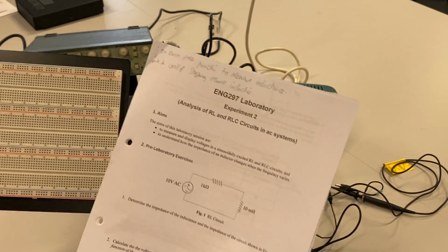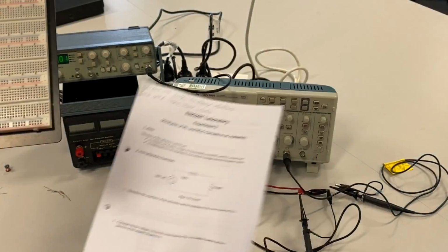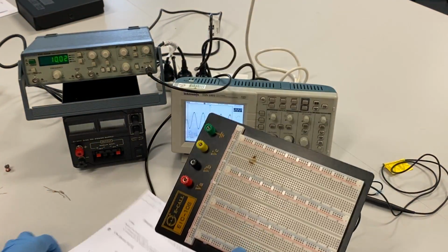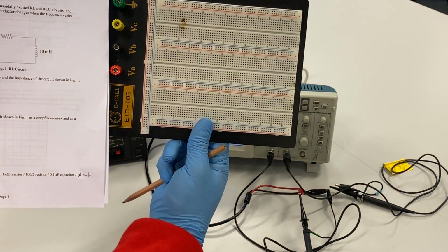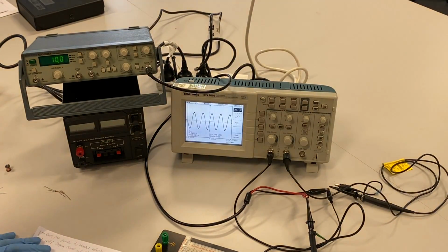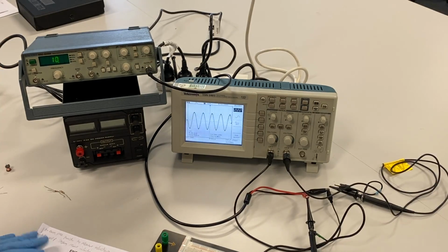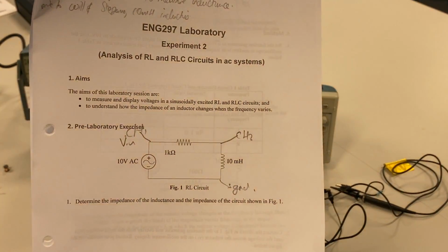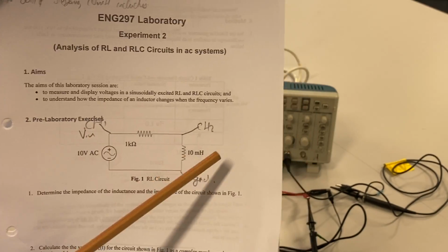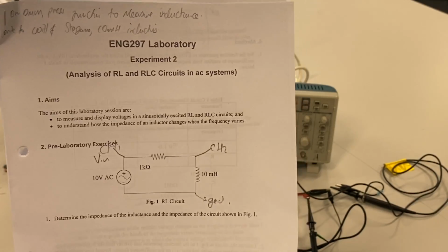So what I always advise is to transfer what you are seeing on paper and move it to the breadboard. I'll hold my breadboard like this, just like paper, right? I'll put my resistor like that, then my inductor exactly like that, then I'll give my input signal there. I'm going to connect channel 1 and the input voltage here, then connect channel 2 across the 10 millihenry inductor, then connect my ground, just like that.